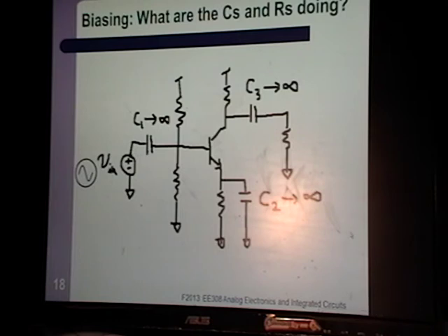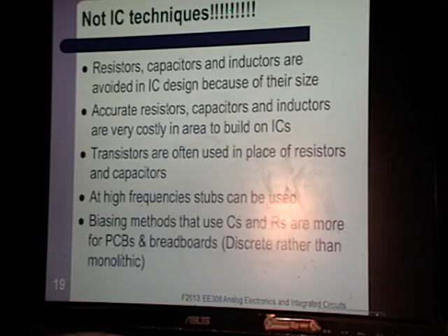And if you dump those negative things on the supply, which is positive, it becomes less positive. You've always taken the supply as sitting at 5 volts, ideal, and ground as sitting at ground and never moving. But what actually happens is every time the clock ticks in a digital circuit, those things bounce around like mad. So you can actually solve that problem by using bypass capacitors. If you put a... let's see what the next slide is.